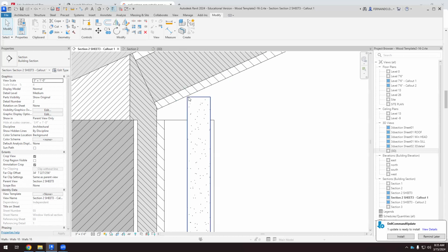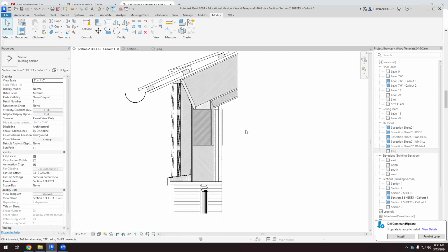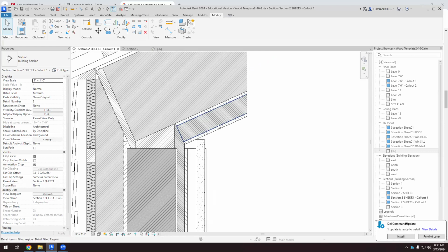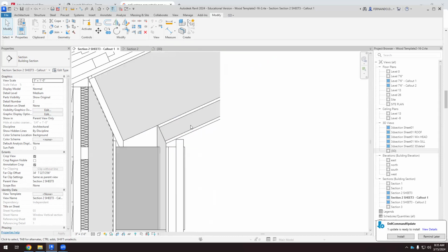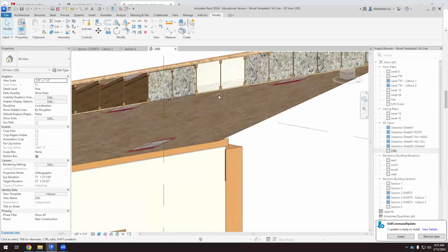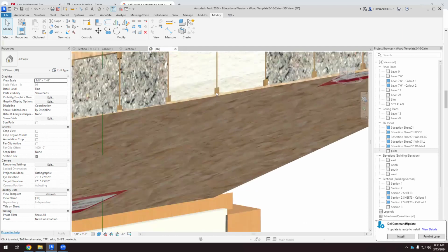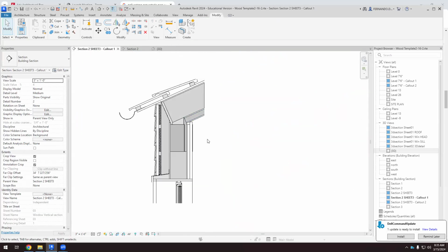So there's always a tiny gap there, but it's okay. So that would be a solution with thermal insulation inside. Okay, so if we have enough height here, we can do that. And now we don't have this thermal bridge that we had here. It's not a 3D component, remember, but now we don't have the thermal bridge that we had with the joists. Okay, so that's an option.